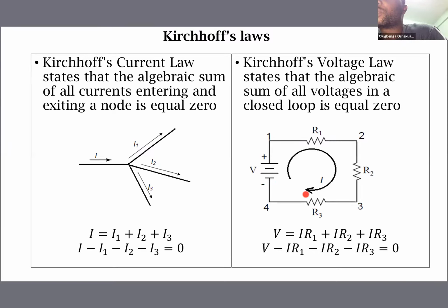through the resistors. What we have learned earlier from Ohm's law tells us that resistors R1, R2, R3 are in series. The same current I will flow through R1 and R2 and R3. But what we did not mention is the voltage drop as the current is flowing. As current is flowing through the resistors, voltage drops.